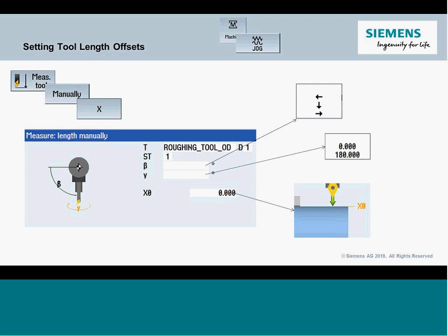And then from there, it's just going to touch off like any standard tool would. Come down to a known diameter, take a light little cut, mic it, plug it in the X0, whatever diameter I'm on, and you've just touched off that tool. And the system, taking into account, obviously, the distance from B rotary center to gauge line, has plugged in that value, like we looked at earlier, from the gauge line to the tool tip for you.